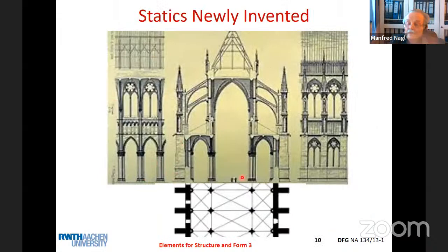Okay, the next is we go in the church, in the main house, and we see the nave and the two aisles. We see the construction outside, the roof, and so on. We see the huge windows of the main house, and here the windows of the aisles. And we see that the stability is based on columns and connected columns, on the one hand by the vaulting, the different segments together, and by the buttresses to these columns on the outside. So this is completely new, and this guarantees stability in a static sense, but it also guarantees stability in a dynamic sense.